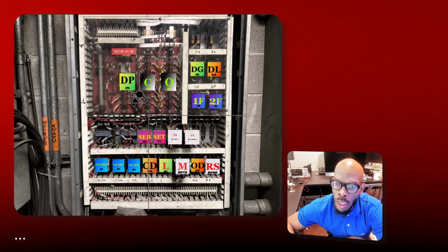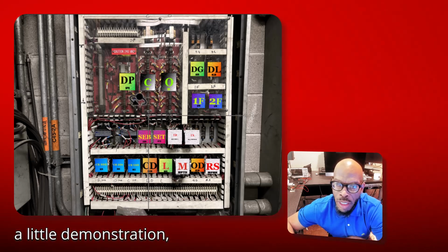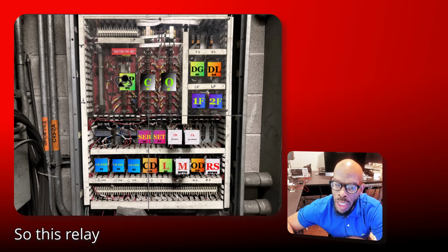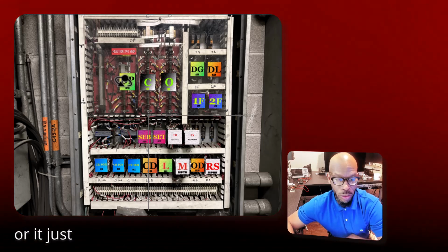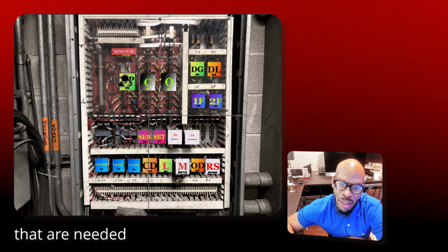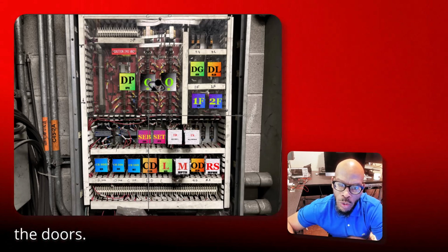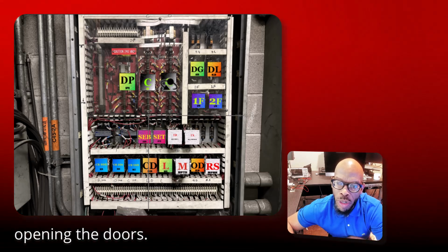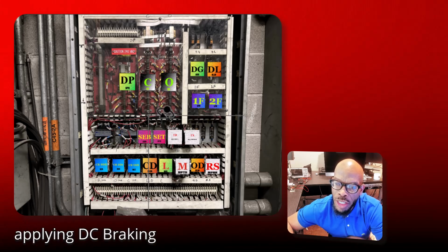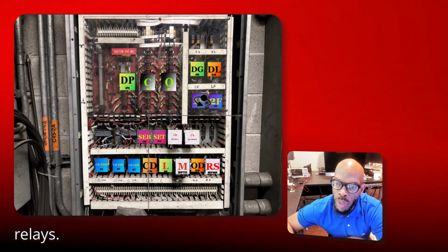These buttons stand for different things, so let's run through them right quick before I give you a little demonstration, and then you can get into the video. This is the door potential relay. This relay right here shows a schematic diagram of the different devices that are needed to get ready to make the door start. This one is responsible for closing the doors. This one has a circuit responsible for opening the doors. These two right here are responsible for applying DC braking to make the doors slow down when they are opening or closing. These two are the floor relays.